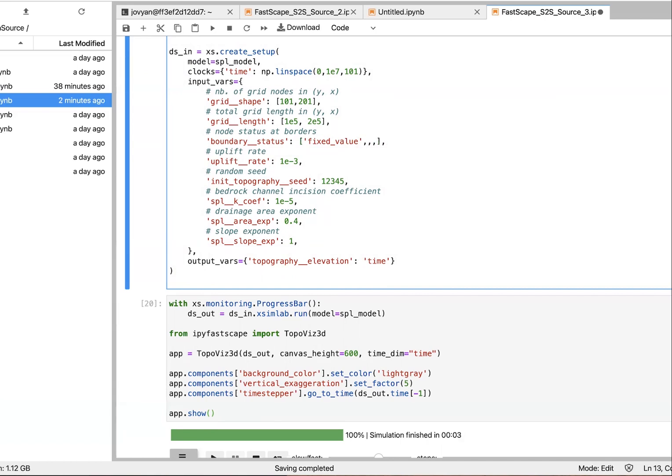So what I'm going to do is on 2 sides, I'm going to make them fixed. And on the other side, I'm going to make them what we call looped. Okay? So if you say more than 1 value, you have to give 4 because it expects there are 4 sides, okay? You cannot say, I only want to say a value on 3 of them, okay? You have to give 4 values. It's either 1 value, which is then applied to all 4 boundaries, or 4 values, 1 for each boundary. And so fix, fix, loop, loop. Let's see what happens, okay?